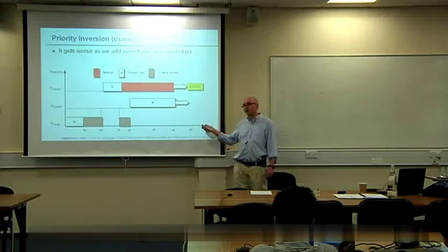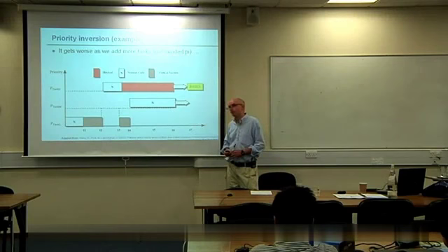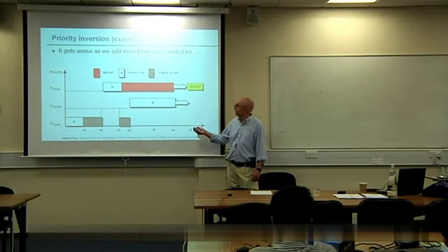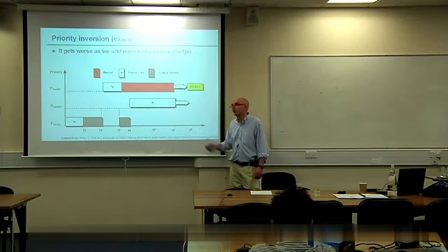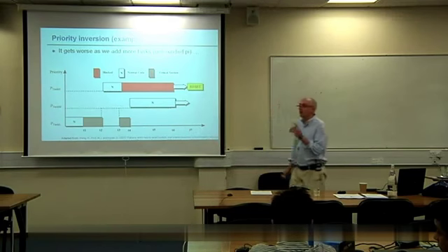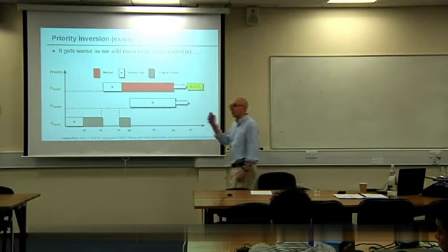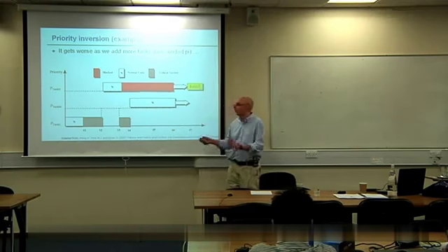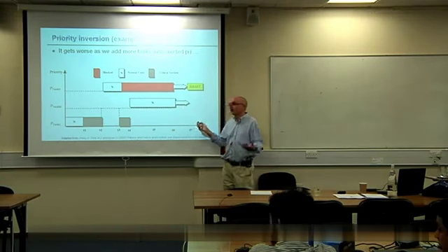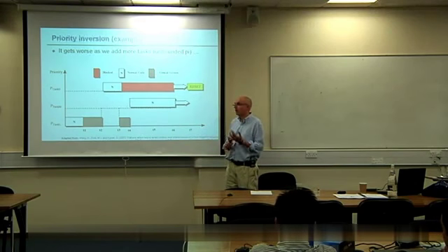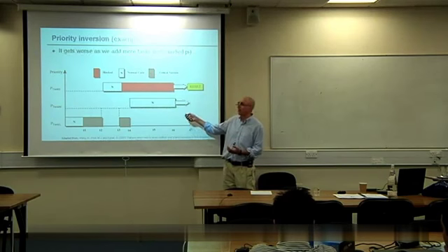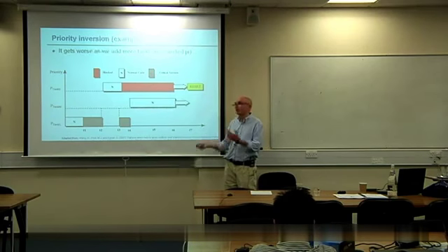There are no critical sections in this medium priority task, so there's no reason why that task cannot interrupt this one. Why shouldn't it? The logic is that it should. The medium priority task doesn't need to use the ADC. So the ADC is locked out, which means that the high priority task has to switch out and give control of the CPU back to the low priority task.